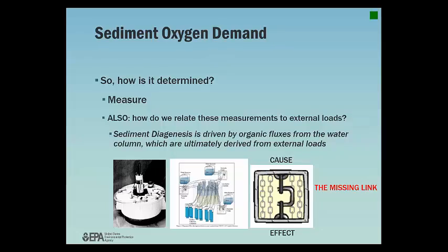Unfortunately, that has no way of relating the SOD to the external loads. So it's kind of critical, because sediment diagenesis is driven by the organic fluxes from the water column, which are ultimately driven by external loadings to the system. What we're missing here, the missing link, is that we know there's SOD out there. We can measure it, but we don't know exactly what caused it and how much came in. So we need to come up with a way to link the cause to the effect.